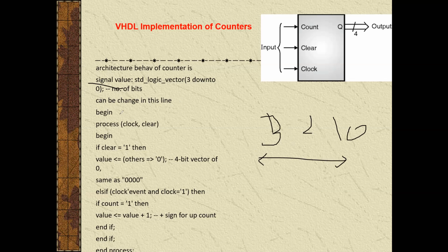Then we have to start with the begin. Begin is a predefined word here, and we have to mention process because it's behavioral modeling. So our 4-bit counter will operate on these two signals, clock and clear, so we should mention them here in the bracket.